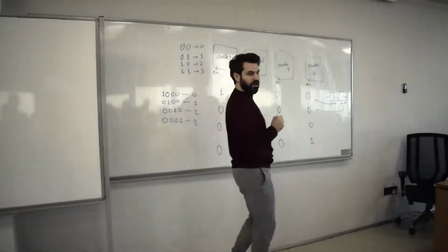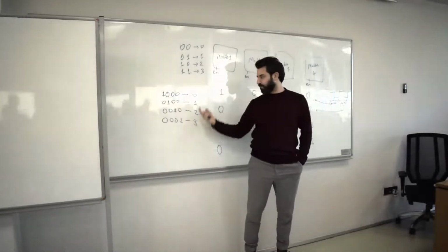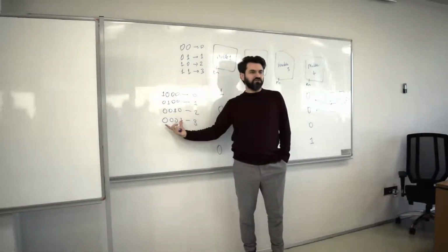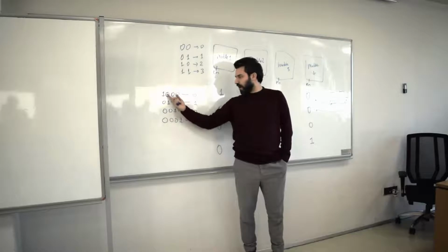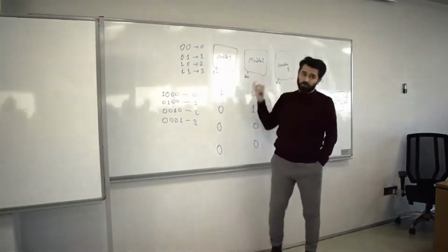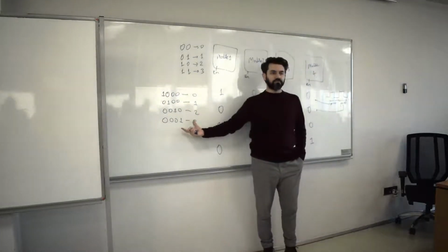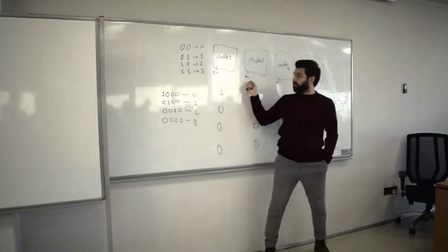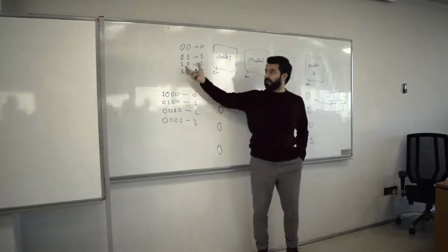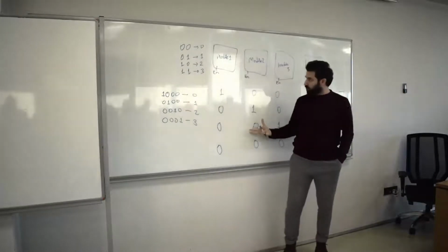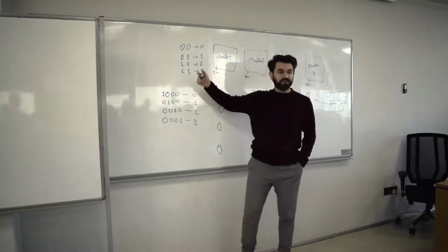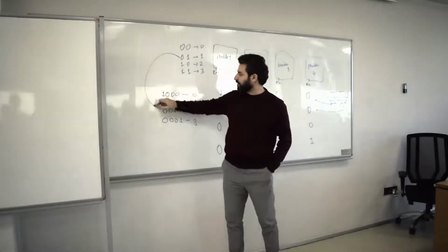Okay, so I now use 4 bits to map to these decimal values. Why? Well, because this is just convenient for me, because these ones can be used to enable different modules in my hardware. I cannot use this counter for this specific purpose because it's not generating those ones in the way that I described these enable signals. All right? But, of course, there is a simple transformation going from here to here, right?